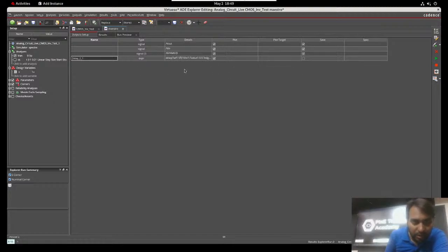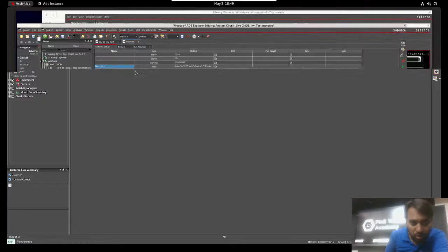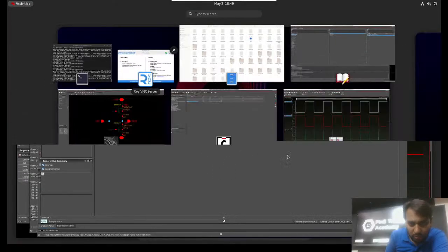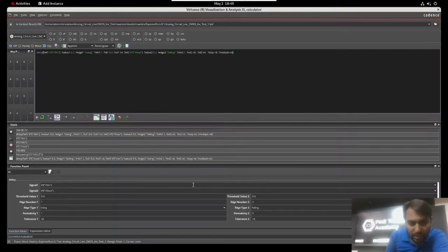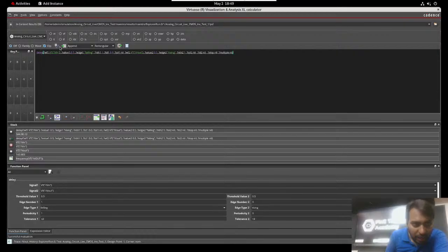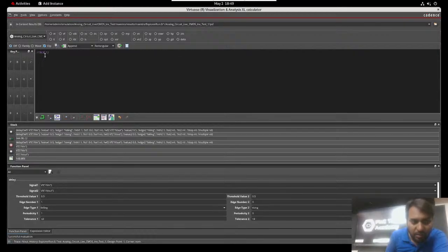Similarly you can go for 1 to 0. Same input, everything is same, just change so that this is falling and this is rising. Okay, and you can press apply here, and now you will find that delay is 178.